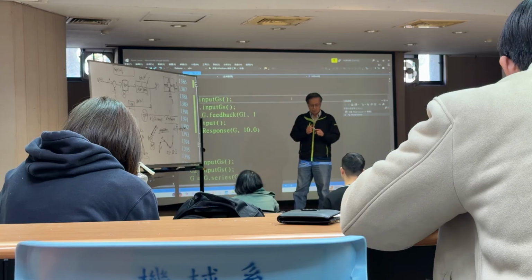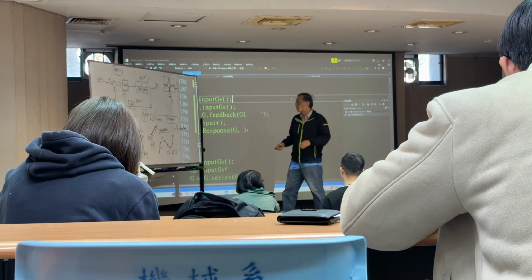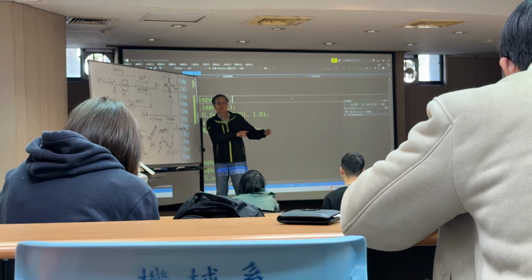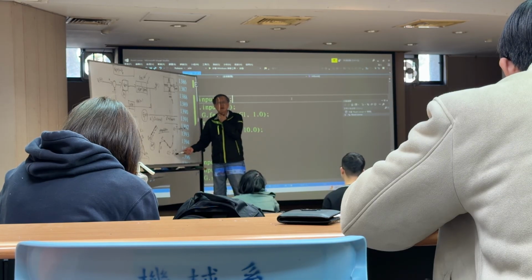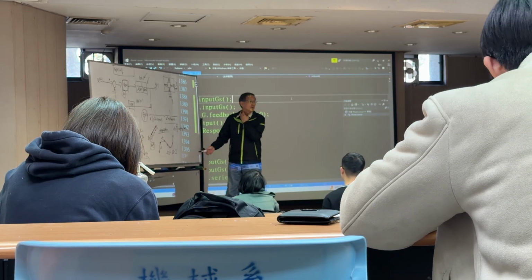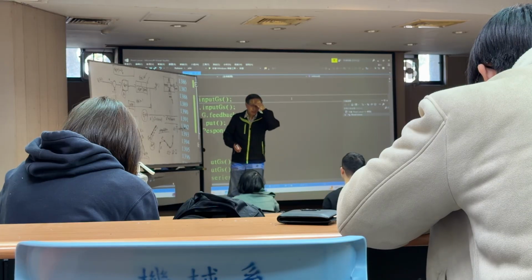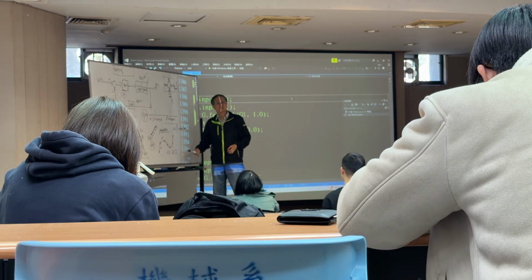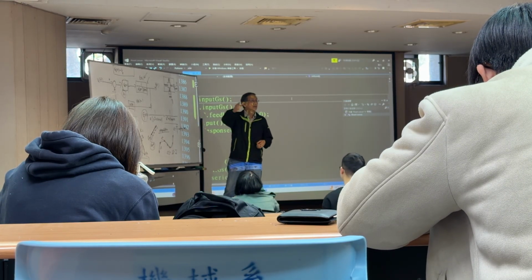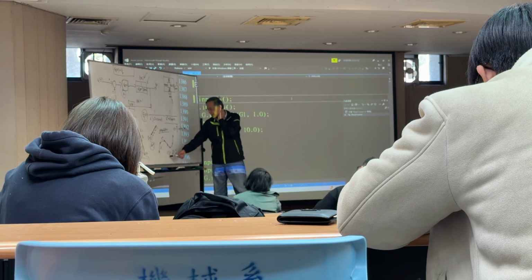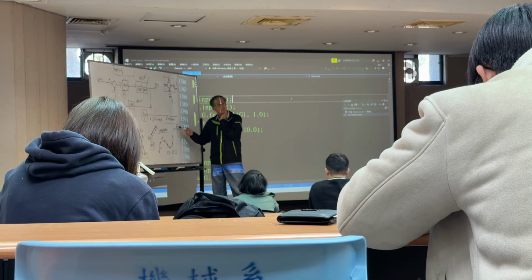So that means, in my software program, the program will ask me, what is your moving velocity? If I give it a very fast velocity, it actually has big errors, remember? Okay? So delta s equals velocity times the sampling time.